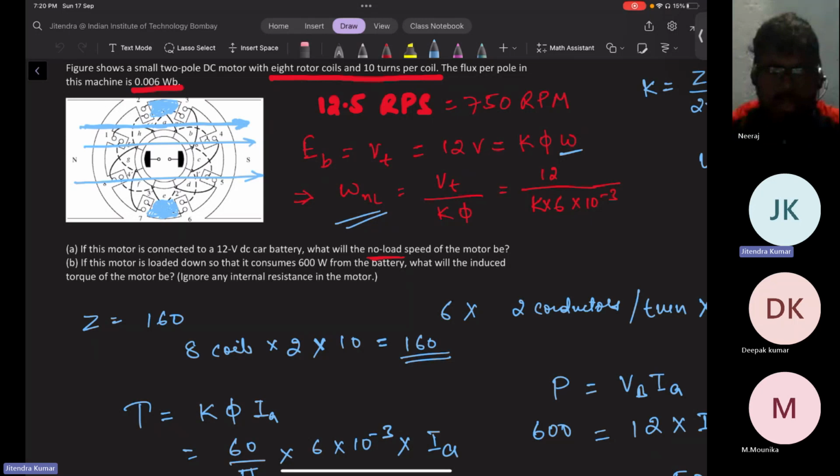Yeah, you are correct that each conductor will participate in the generation of EMF, but at different instants of time, not at the same instant. Let's see, this armature is rotating, right? Yes, sir. When this portion comes under the influence of this magnetic field, it will definitely generate EMF. But at this particular instant, at this particular position, it will not happen for that portion. After a certain millisecond or microsecond, some other portion will go there and that will get linked.